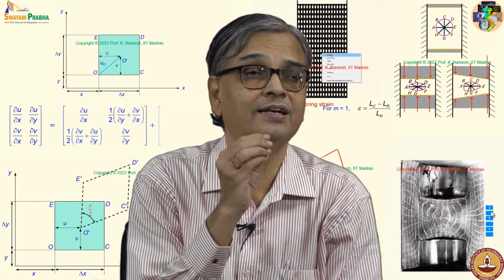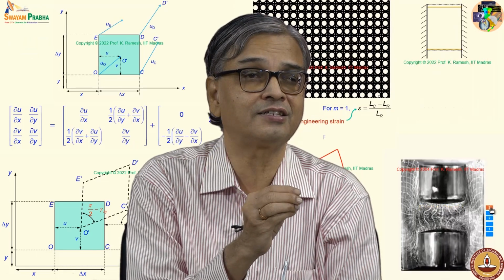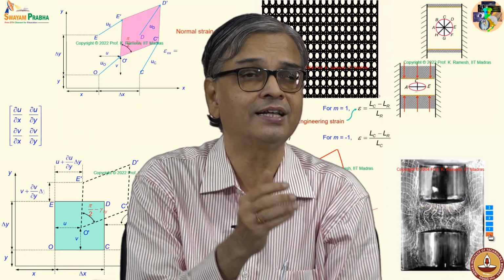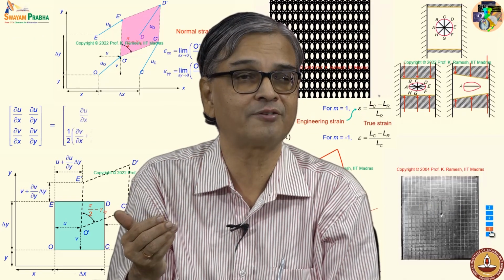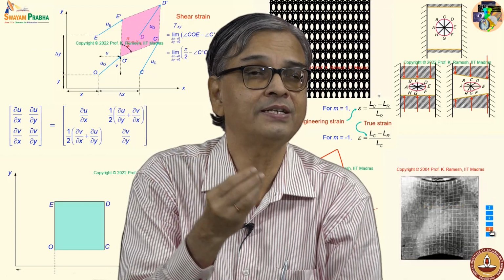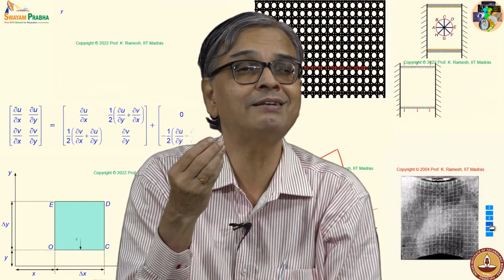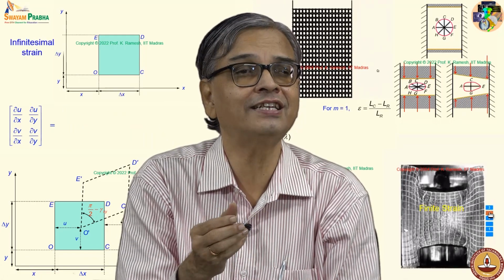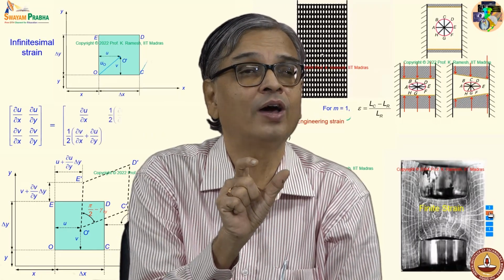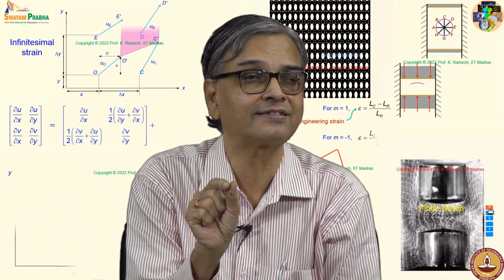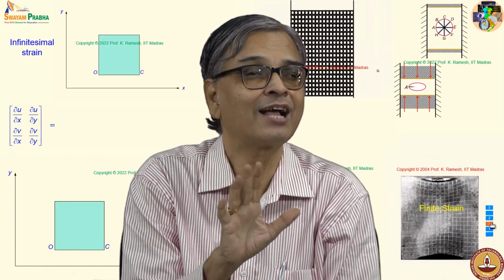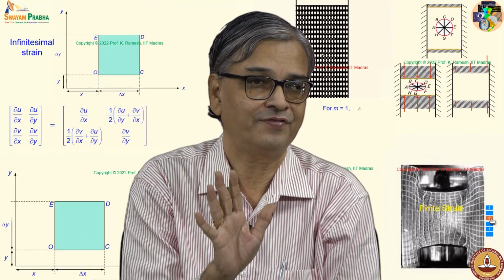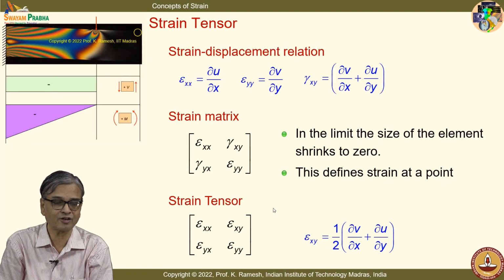Whatever stress transformation law we have looked at, I will have a counterpart as the strain transformation law. If you have looked at principal planes, I can also have principal directions here. Instead of a plane, you have a direction in which the element only elongates or contracts. It does not undergo any angular change. Fine, so all these are similar concepts.